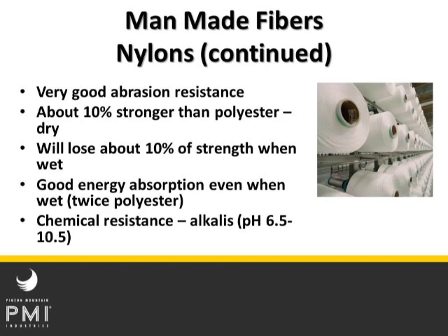It's twice the energy absorption of a polyester rope. And its chemical resistance, it tends to alkalize a little bit better than it does acids. But if you look at that pH range, 6.5 to 10.5, that's probably not a bad range to work in for most people anyway. If you're working on stuff outside of those ranges, you're probably not going to be very happy about it for very long anyway.